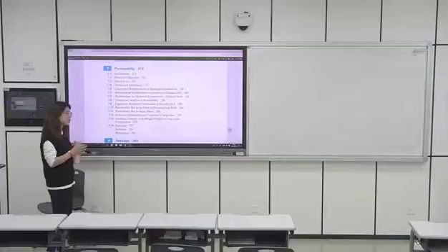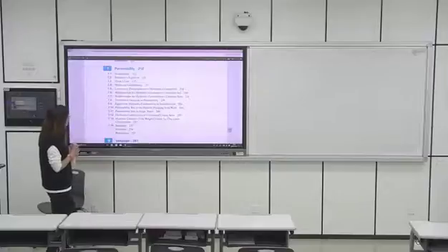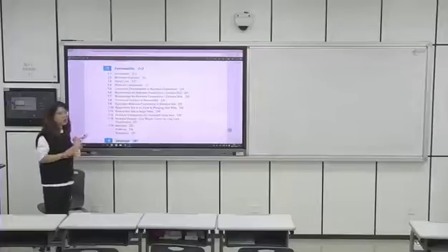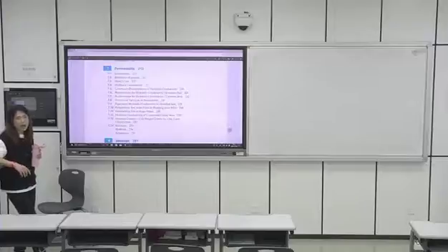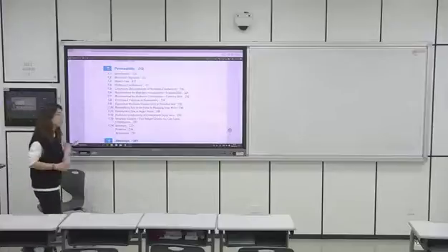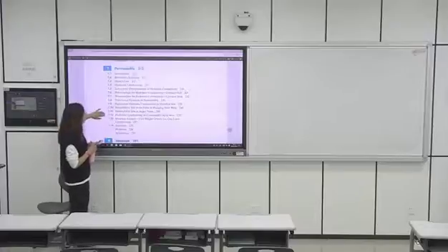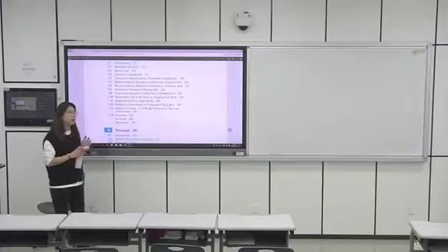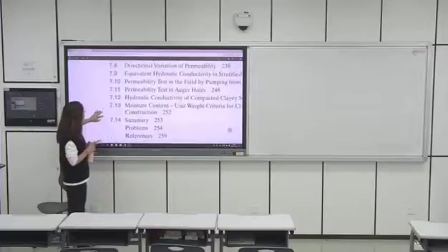And then we learned how we get the hydraulic conductivity. We have the constant head test and another one, what? The constant head test and the falling head test, right? In the laboratory. Those two tests are related to the size of the specimen, and we have equations for those two methods to calculate the permeability of the soil, right? And then we learned some methods to conduct a field permeability test, right? This is the permeability.